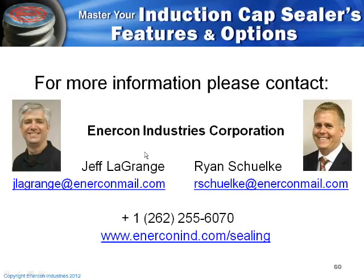We have another question related to sealing heads, and the question is, with the same power supply, could a different sealing head produce a more efficient seal or allow the packager to go faster? I would say absolutely. If you've got a Super Seal 100 and you've got a coil that maybe is not optimized for the type of cap that you're using, it may be able to seal it, but if you go ahead and get one that's really designed for that type of cap, you will definitely get higher performance and higher speeds out of that optimized coil.